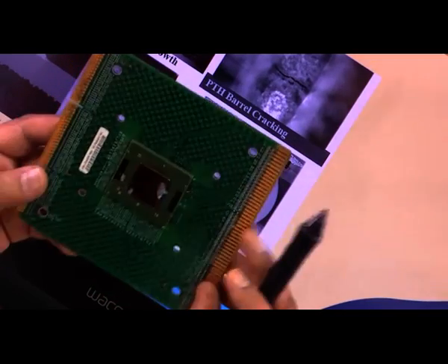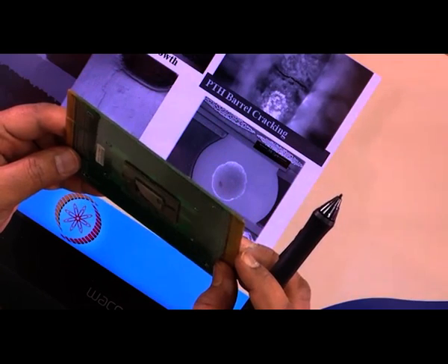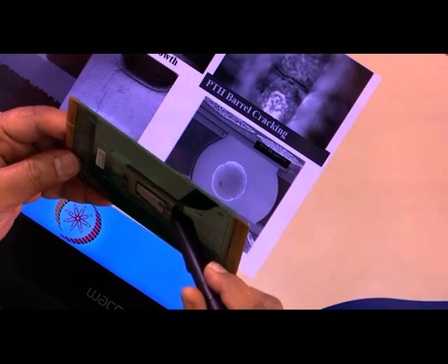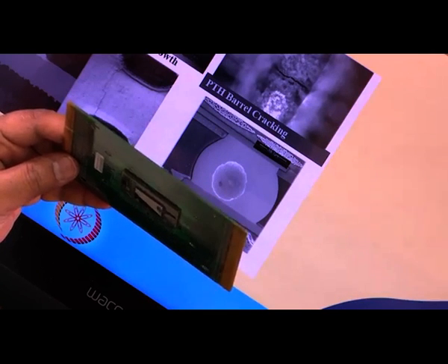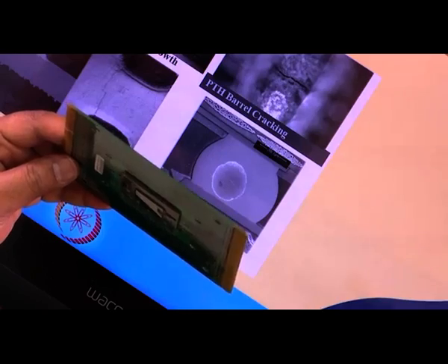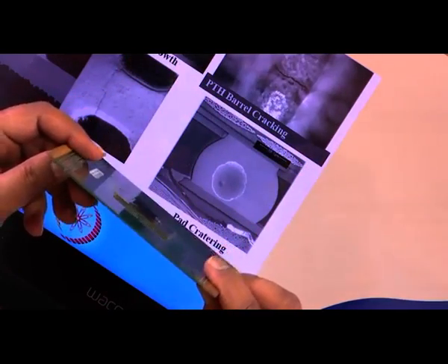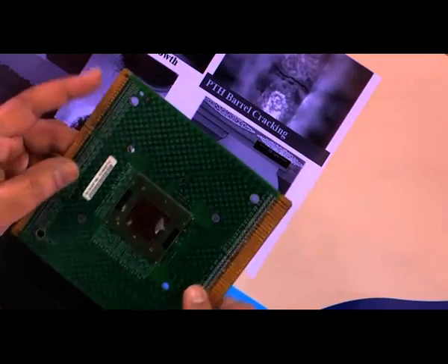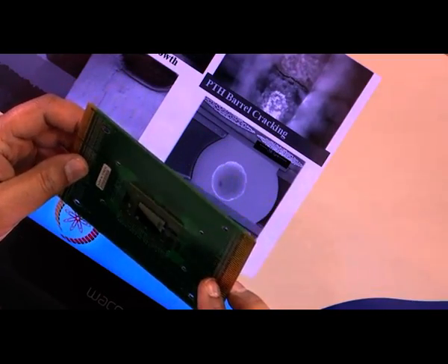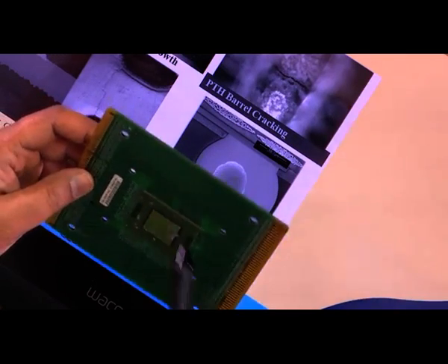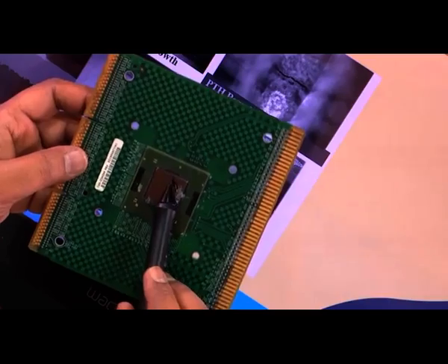Now, if you look carefully from the side, I do not know how much, probably yeah, you can see the outer, if you look along the edge, you can see the series of solder balls, right, at least the outer, the last row of the array. Other end also you should be able to see, but again this end was more clear, right. However, I do not see that outer joint over here.